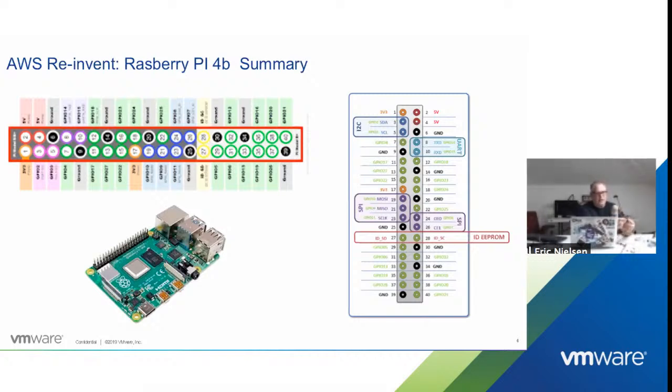It's important to know that, because when you're using the Raspberry Pi like I am, outside of a case, and I've got it powered up, you have to be careful. These sensors have a power and a ground, and you can't arc the ground pin on the sensor. See these little pins on the edge? You won't be able to see it. Those are live pins, and if I touch those onto the metal, that'll be taking power to ground, and it will cause the Raspberry Pi to reboot at the least, and you could burn out your sensor, and you might also burn out the Raspberry Pi.